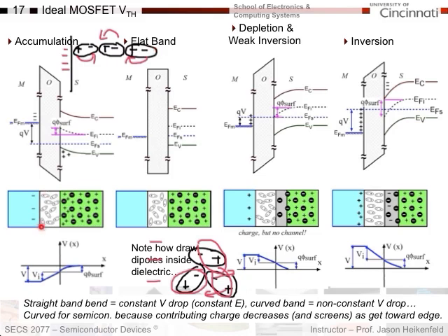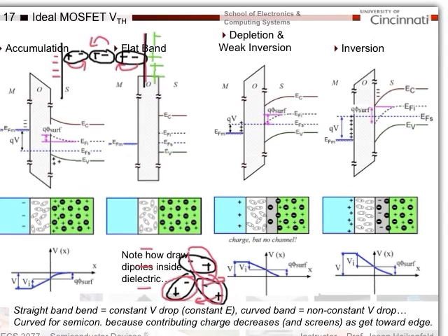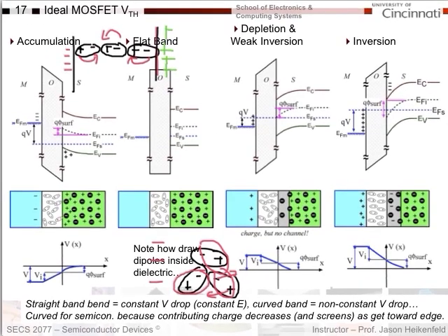So now you're getting a glimpse in terms of how a dielectric works as well, in terms of negative charge getting to the other side and then showing up as positive charge on the other side. Because of course, on the other side of this dielectric, okay, this is the end of the dielectric, wrong color there, then I would start to see positive charge showing up over here, because I've got negative charge here, and so the positive charge is attracted to the negative charge. Okay, so that was accumulation.